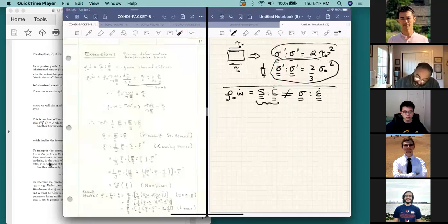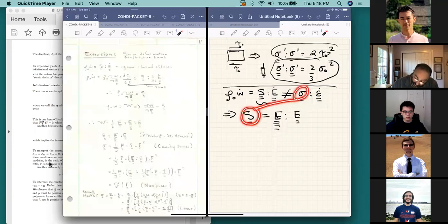And if you go through the algebra here, and I don't want to go through that today, it's relatively straightforward. What you find out is that the implication of this is that S must be equal to E, the same E that we have in linearized elasticity, but multiplied times the Green-Lagrange strain. So there are 2 things that are different about this law. You have the second Piola-Kirchhoff stress instead of the Cauchy stress. You have the Green-Lagrange strain and its time derivative, by the way, instead of the deformation variable being the strain deformation here.